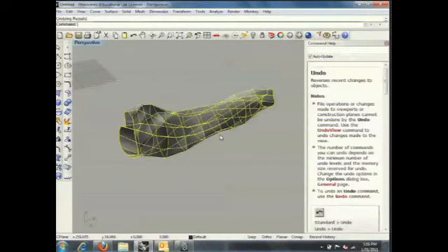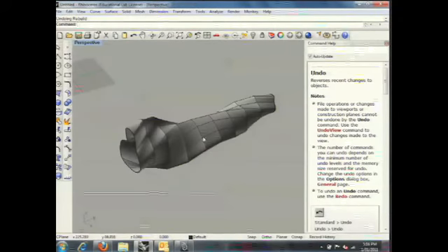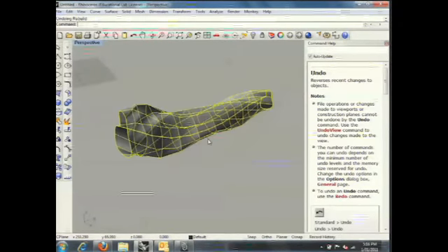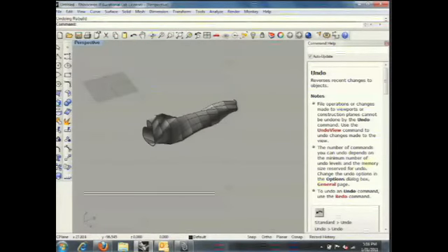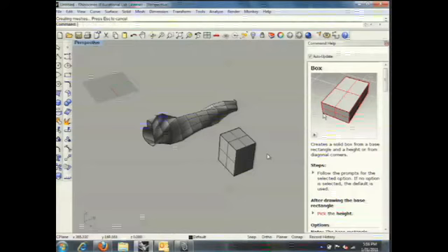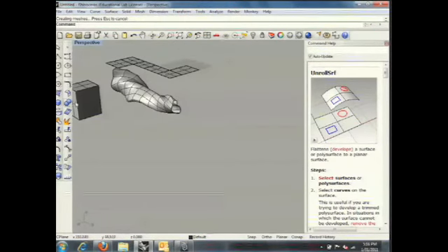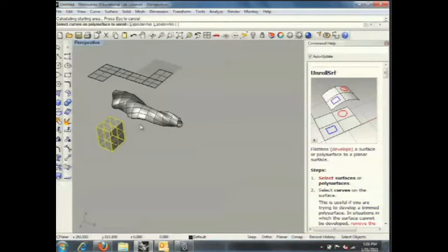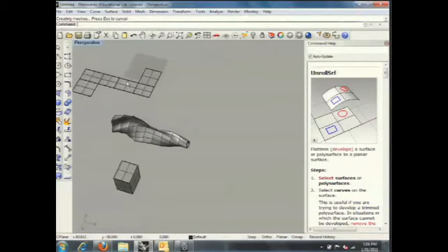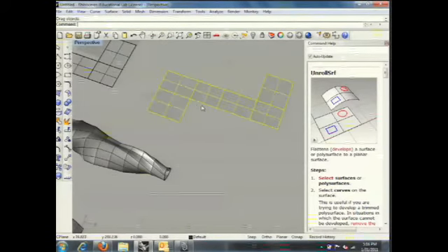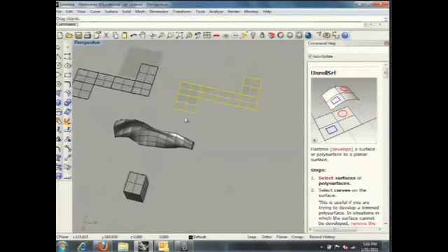One thing I want to mention is if you want to do an unroll command directly to this surface, it's not going to work, because, see, this is how Rhino works. If you have a simple geometry like a box, if you do an unroll surface, you can pick up this geometry. You don't want to explode the surface, right? This option will be no. Click enter. It basically creates the surface like that. Okay? So it flattens this cube, the box, into a sheet. Later you can fold it back.